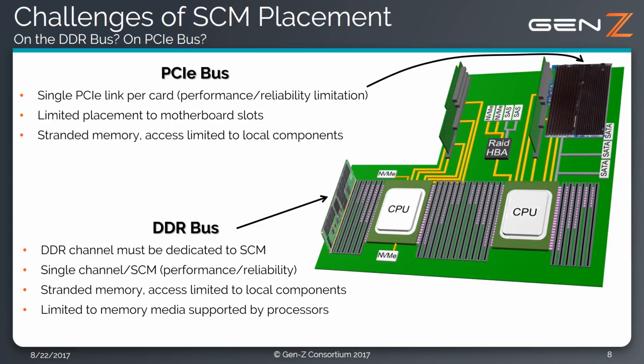These DIMMs are called NVDIMM-N. They typically have lower capacity than standard DIMMs because of the persistency circuitry, but they are very fast and operate well on the DDR channel. Another type of NVDIMM are NVDIMM-P DIMMs that utilize storage class memory natively.